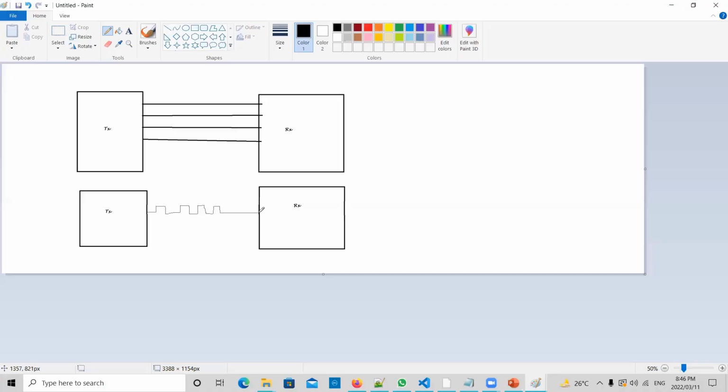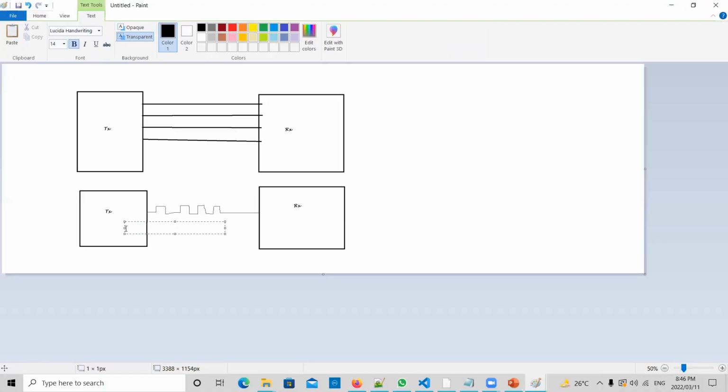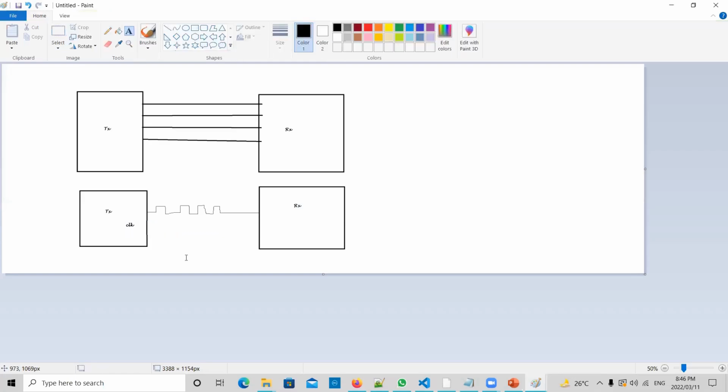What is a boundary for one bit? For that, they will use another signal called clock. The clock is needed to do a serial communication in the earlier days. If I send one pulse of clock, I will push one bit. So the receiver has to see, at that clock pulse, what is the value of the voltage.